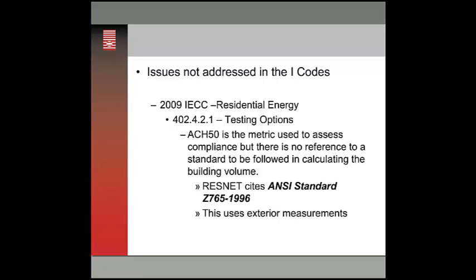My 2 cents on it is that really that information should be submitted when someone submits plans for approval on new construction. I mean, these are new construction codes, so the builder or the architect or the designer is submitting plans for initial plan review. My 2 cents is that should be submitted right up front, that there should be no disagreement, and that information should be readily available to whoever's doing the actual performance test. I think the last thing you guys want to do when you get out into the field is spend an hour plus calculating building volume.